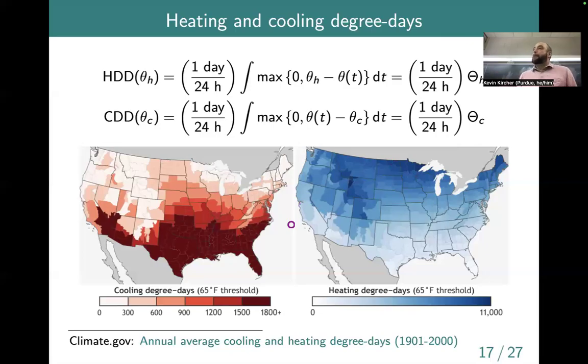Yes. Two questions. I guess, remember we're calculating. We agreed, if we didn't go through the other method, would we just take the number of days? Like, if I wanted to see the heating degree day from today, I would take the temperature of today minus 65, or the other way around, the difference between the day and 65, times 1 day. And if I do it for the last 2 days, then take those temperatures and average. And I get a certain number of degrees per day.